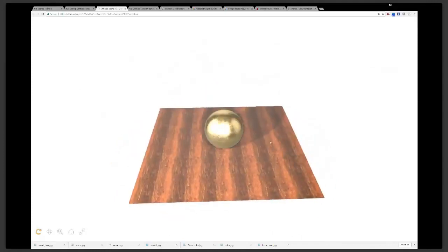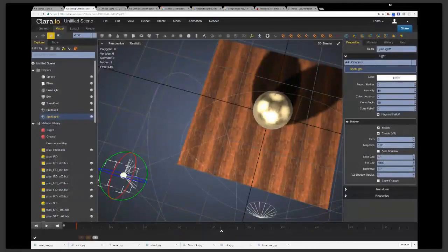We can see here that they're a bit jaggy. You can just fix that very easily. Just change your map size. I wouldn't go too high, but 1024 really is nice.